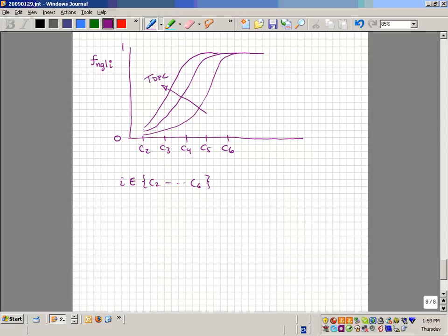So basically what it says, if you take, for example, C4 and you take low temperature, the lower the temperature, this might be minus 40, and this might be plus 20. So for C4, you're getting basically all of it out with the low temperature, 95% recovery as a liquid. Here we're getting 60% recovery as a liquid. Here we're getting 25% recovery. And if you go to 80 degrees, then this is just a flat line, because it's at equilibrium. It's an equilibrium gas at 80 degrees C. It's a flash gas, so there's no liquid precipitating out at 80 degrees.